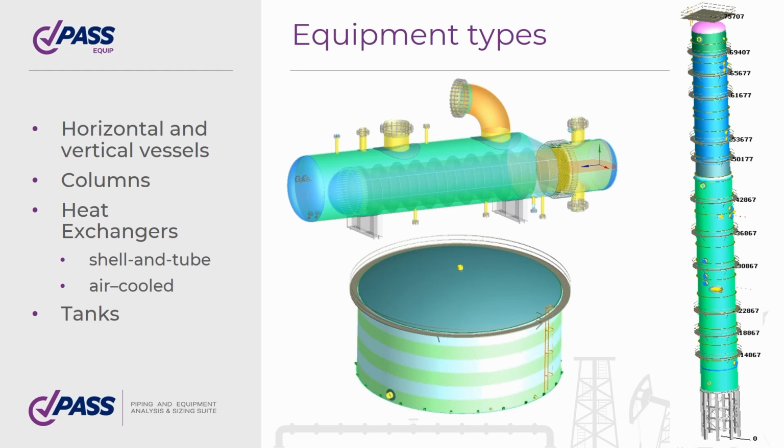The calculation is carried out for certain standard elements such as shells, heads, nozzles, flanges, supports, etc. If the construction is not described in any standards or the application conditions are not met, you must use design by analysis. Design by analysis is a stress calculation using numerical methods, mainly the finite element method. This method allows you to calculate almost any construction with any loads.